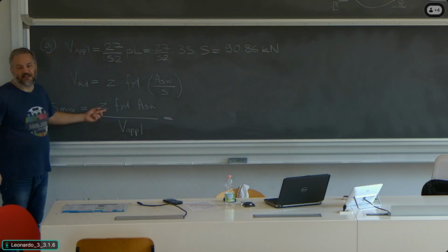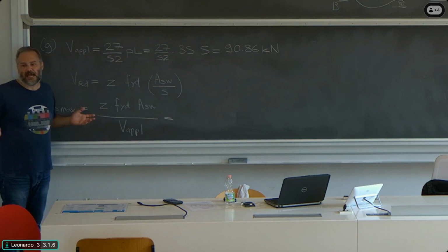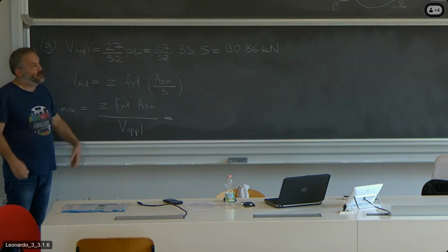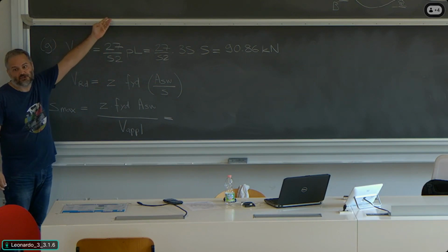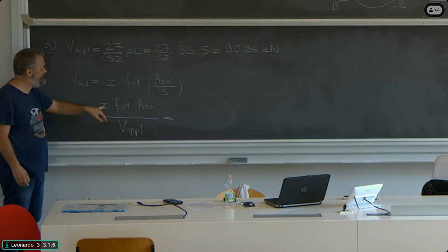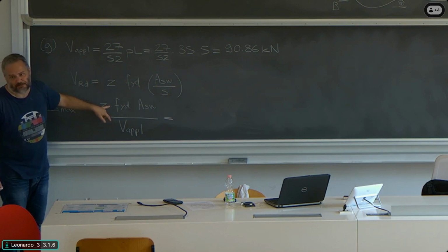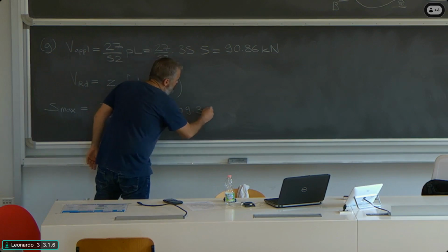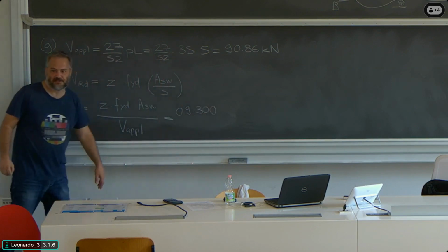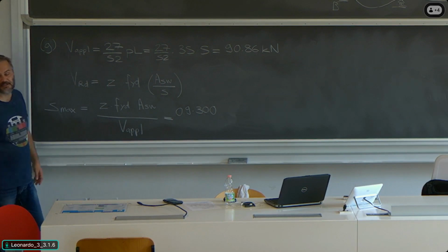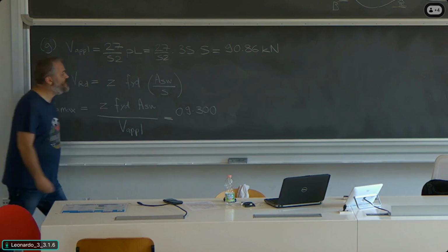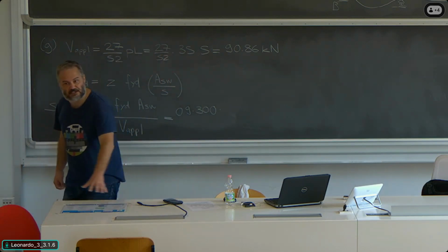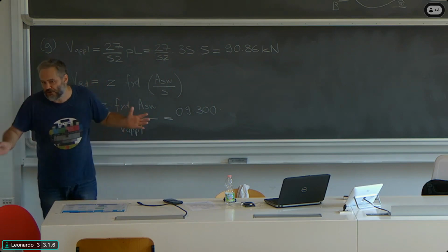What is internal lever arm? We have no information at the point where we calculate the shear, so to the right of support B. I mean, we could assume to use the previous reinforcement, but to calculate Z in an accurate way doesn't make sense. We use the approximate formula, which is 0.9 times 30 centimeters, which becomes 300 millimeters. Again, work in millimeters and newtons. Then design yield strength, it could be different between longitudinal reinforcement and stirrups. It is not in our case, so 350 is okay.